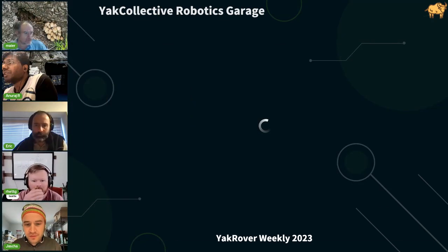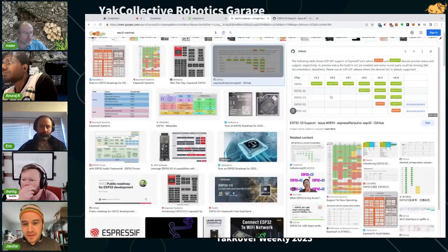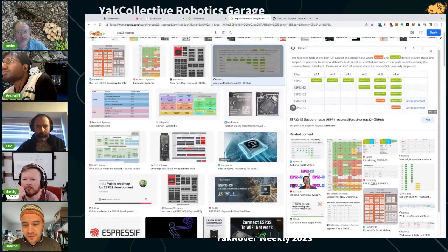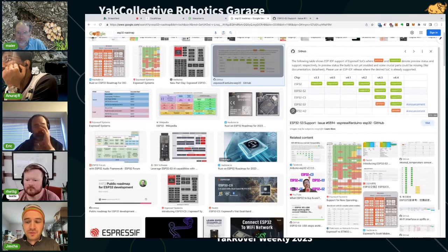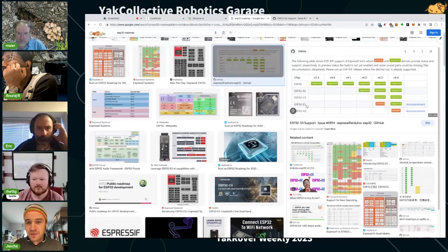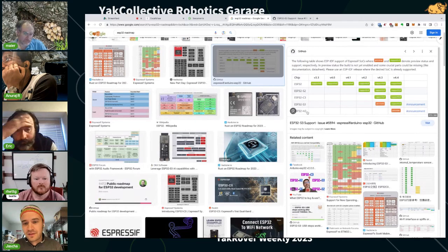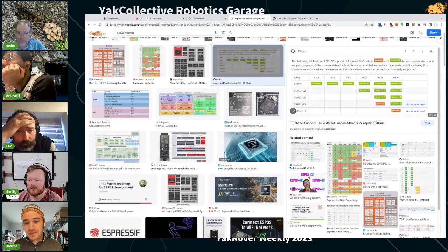So Espressif has several different models of the ESP32. And the thing that is very frustrating is that it's not like the S2 versus the S3 is just a new version of the old one. Those two chips specifically have some differences in the silicon: there's some stuff in the S2 that is not in the S3 and the other way around. So they're all kind of different, which makes it very annoying, depending on how nitty-gritty you're getting down into all of the features of the chip.